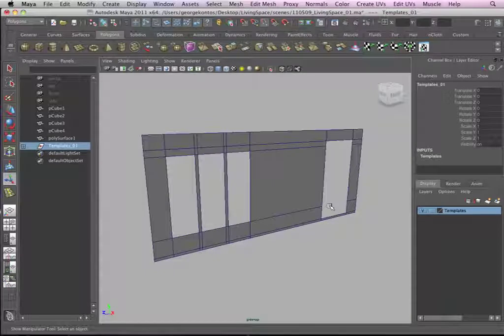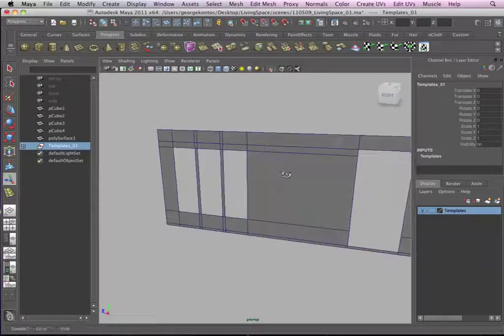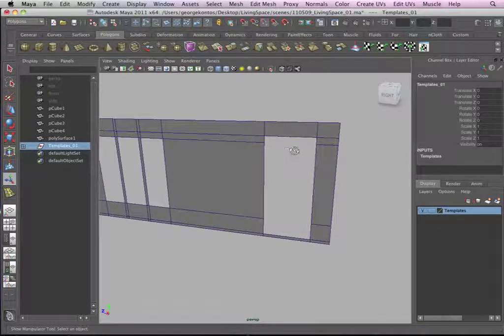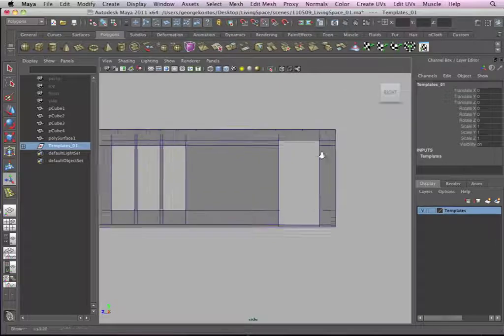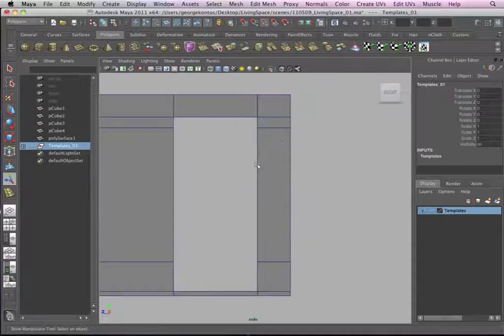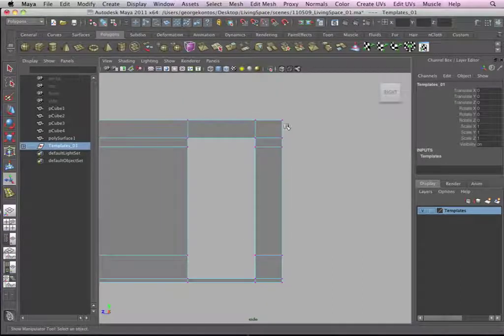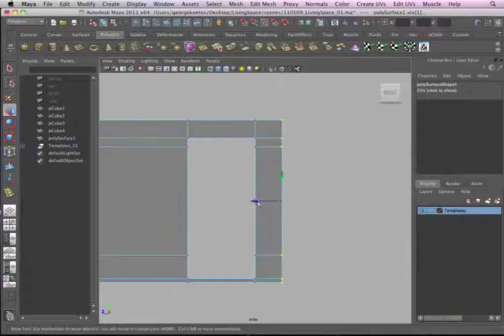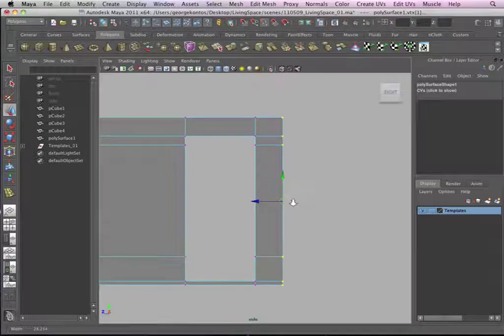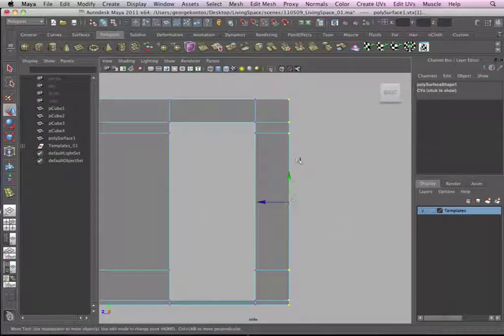This will save you a lot of time, and this is a good way to organize something and keep working on the wall spaces and keep adding. Let's say you want to add something. I forgot, I wanted to add a little window over here, next to the door. No problem. I'm going to go to my side view. And I don't need to bring any placeholder. I just have an idea. Actually, I want to increase the width of this wall. Notice that I have the snap on. Make sure you turn off the snap.